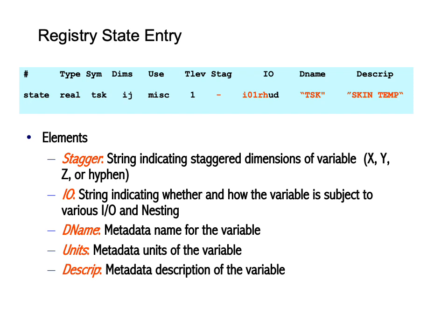The data dictionary part of this is that there are portions of the registry that are not the final arbiter of what is actually going on inside of the WRF model. So it is convenient to put in units and description that will help you remember what was going on inside of the WRF model when you put this variable into the registry.